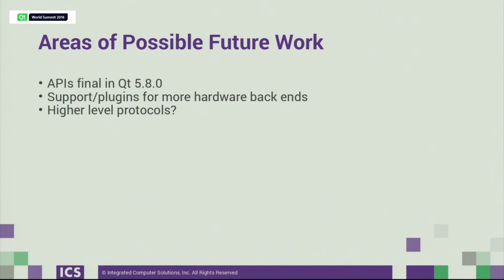for maybe some more of the common controller boards. Another possibility could be some other serial protocols might be added to the module. A couple that just come to mind as possible serial protocols could be SPI and I2C that are commonly used on embedded systems. So that's a possibility, although those are kind of more real-time protocols that don't always run on the same processor as where you might be running the GUI.